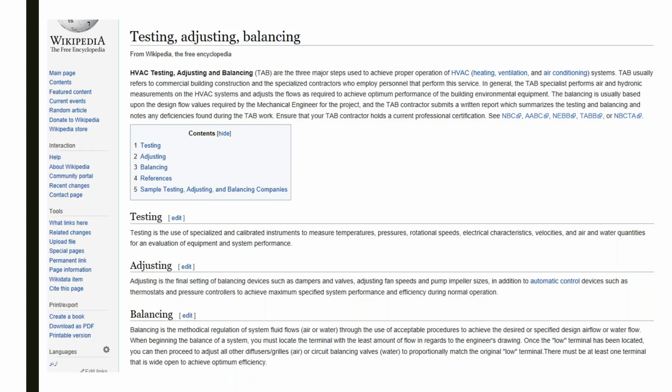So I was talking to them about how it works and how you plug in and how you set it up. And they kind of perked up when I said set it up. After a little bit of investigation, I found out that they were replacing their failed, quote unquote, failed VAV controllers with the same VAV controller. They just unplug and plug in the new one. But they were not making the adjustments and the settings for the new ones. They just pulled them off the shelf, stuck them in the VAV box.